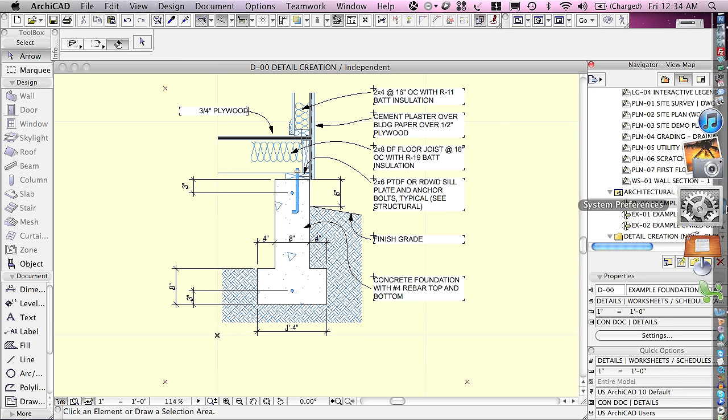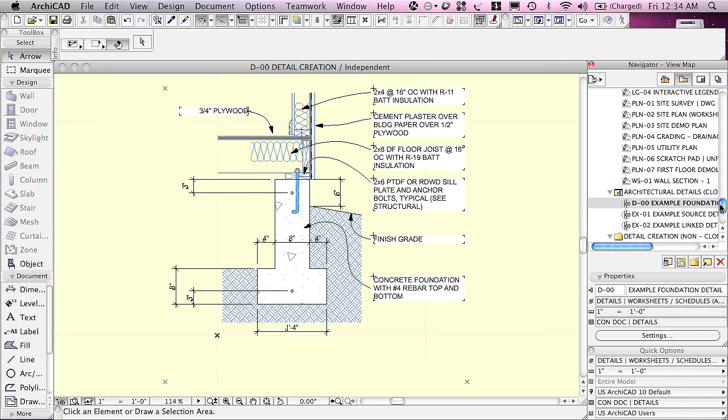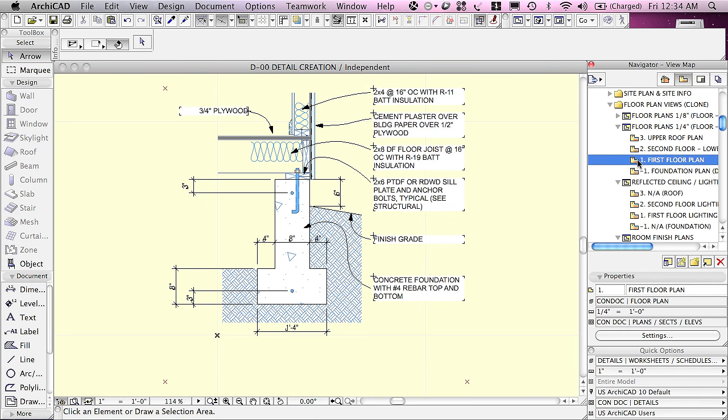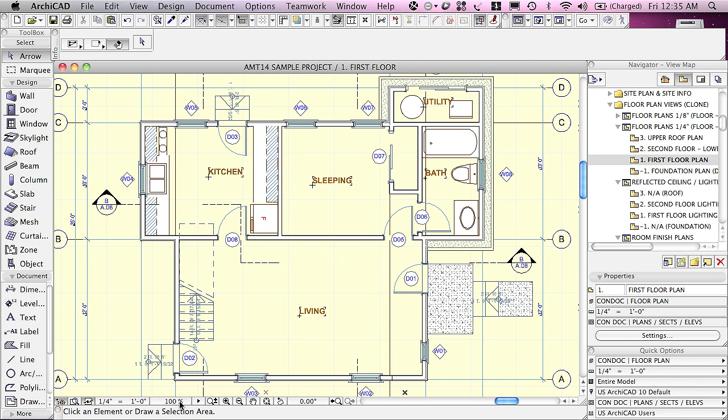And when I go back to, for example, the floor plan, we'll see that the floor plan was at 1/4 inch scale, which is about 1 to 50. Now, right now, we're almost at natural size for printing. If I click on this, it'll put it at 100%.